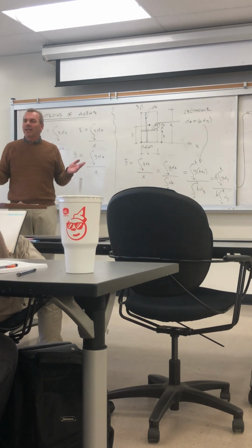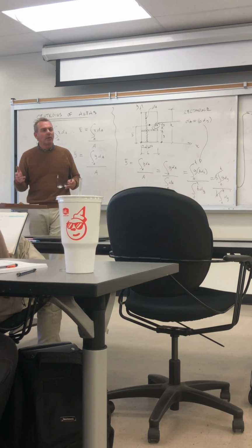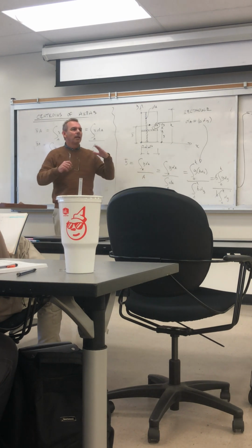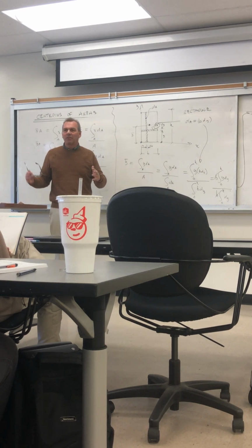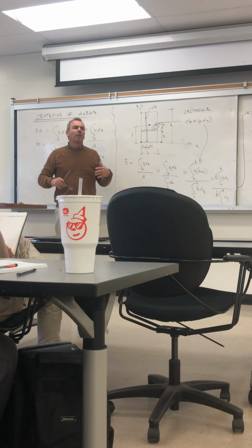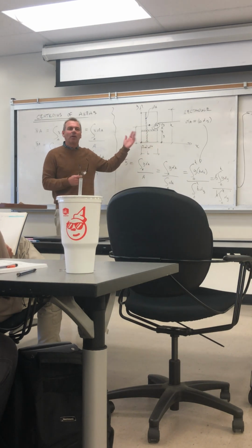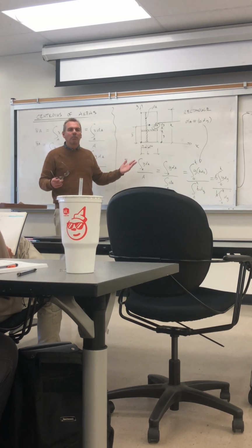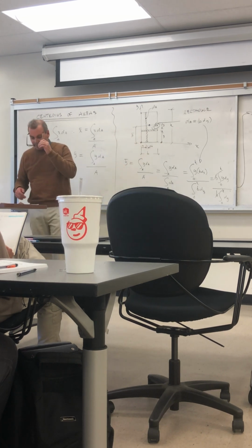So anyway, centroids, and I did this by hand. This was last night. There were about 30, 40 different steel plates I had to include in my calculations. Some of them are 2 inches thick steel plate, and I had to add up all their weights. And this is in 3-dimensional geometry too, not just 2D like this. So my point is that knowing centroids, not just of areas, but of weights of plates and so on, is important, right? It makes a difference.